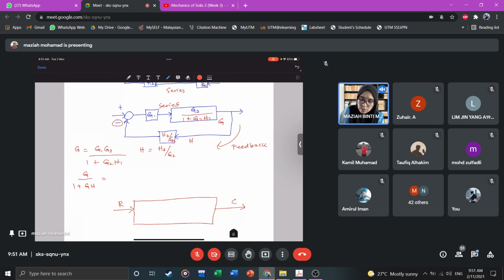So our equation will become G1 G2 over 1 plus G2 H1, divided by 1 plus G1 G2 over 1 plus G2 H1, multiplied with H2 over G2.